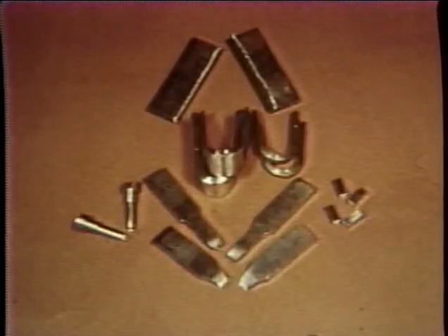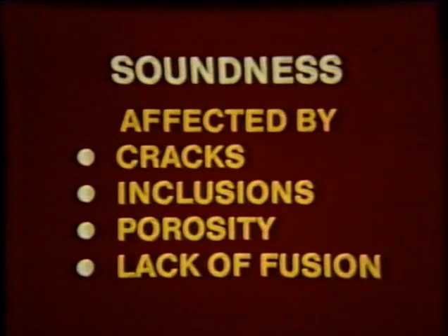Destructive testing is an evaluation process for weld or base metal specimens and takes place during or after the destruction of the specimen. Destructive testing is a function performed by quality control to measure the properties of metals and welds, of which soundness is one of the most important. The term soundness is commonly used to describe the weld's degree of freedom from discontinuities. Cracks, inclusions, porosity, and lack of fusion reduce weld soundness and may prevent the weld from performing in service.